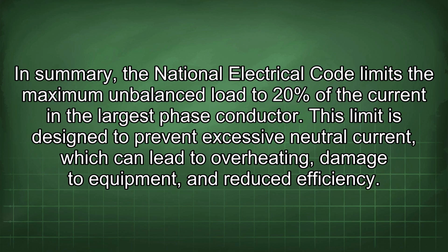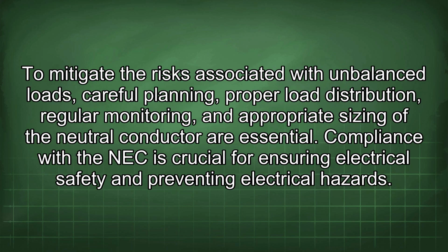This limit is designed to prevent excessive neutral current, which can lead to overheating, damage to equipment, and reduced efficiency. To mitigate the risks associated with unbalanced loads, careful planning, proper load distribution, regular monitoring, and appropriate sizing of the neutral conductor are essential. Compliance with the NEC is crucial for ensuring electrical safety and preventing electrical hazards.